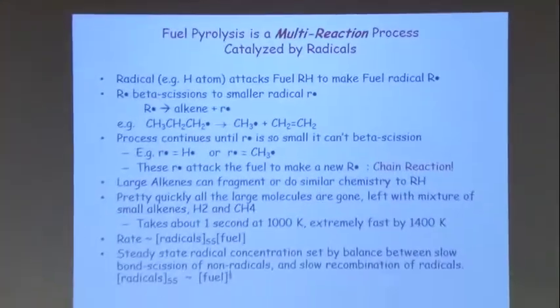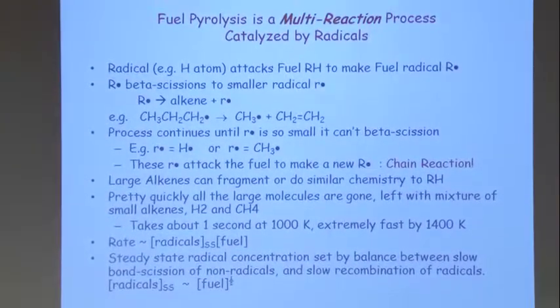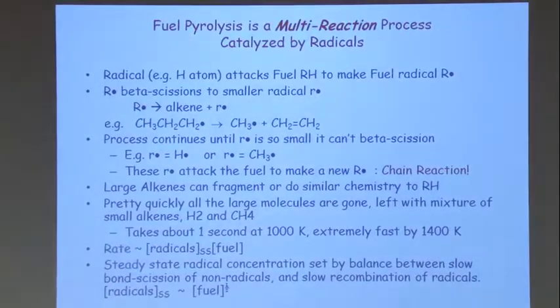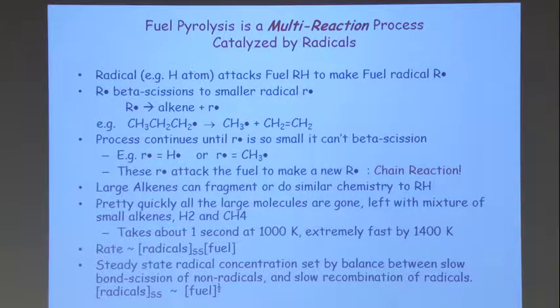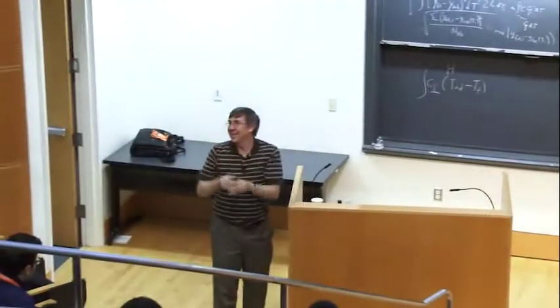So in the chemical industry, this is big news, and they spend a lot of time on this process. And they would like to run at a higher temperature, and they're 100% limited by safety, because if the pipe gets too hot and it fails, then you have a major problem. You have a very big pipe full of a lot of fuel that you're shining into a furnace at 1100 Kelvin, and then suddenly if the pipe opens, anybody who's within a mile of the place is likely to be dead, because you get a really big fireball. And this actually kills maybe about 10 people per year around the world when one of these pipes breaks. So they're very concerned about the safety of trying to keep the pipe not too hot.